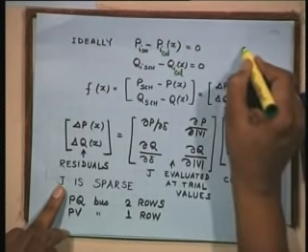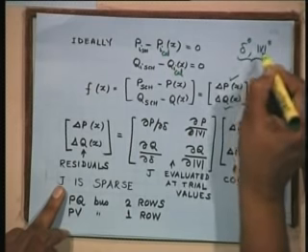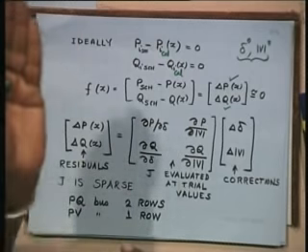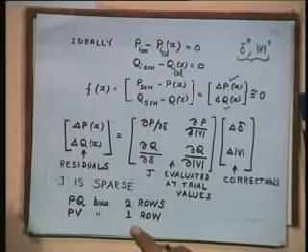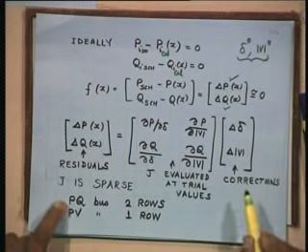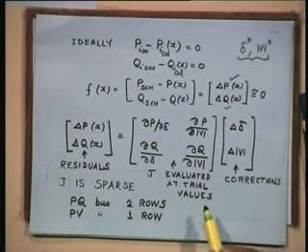You have assumed certain delta 0, you have assumed certain V0. Now, this has to be corrected in every iteration, updated, modified, so that we march further towards our goal. What is our goal? Goal is to achieve a converged solution, the final solution, the correct solution. Now, this Jacobian is known to you because this can be evaluated at trial values at x is equal to x0 or p is equal to p0 or q is equal to q0.